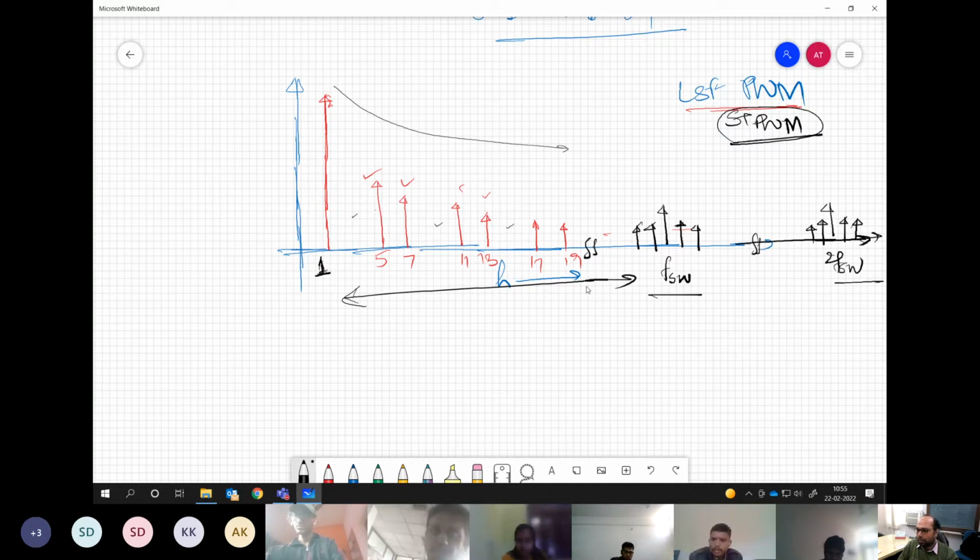So there will be a huge gap between the fundamental and the other harmonics which appear in the system. When you don't maintain the half wave symmetry in the case of sine triangle, which harmonics would you see? You would see even harmonics in this set. That may sometimes be harmful when we are talking about the grid code. Some restrictions are there on how much even harmonic you can inject in the system, whether this even harmonic is as low as second order or fourth order or something like 52nd order or 100th order. You understand the point?